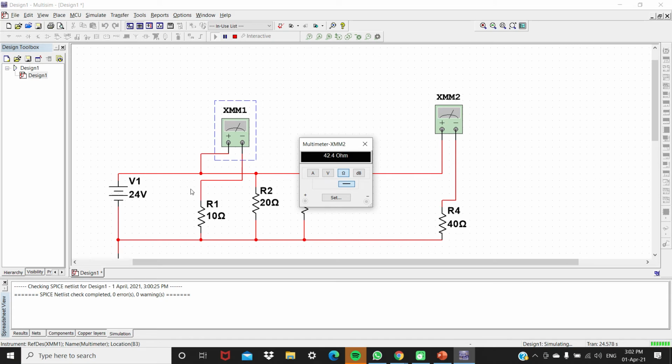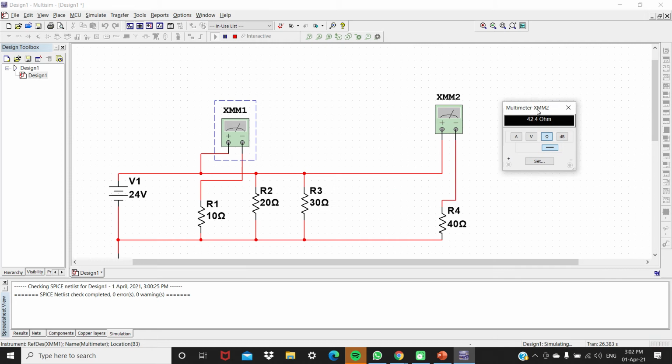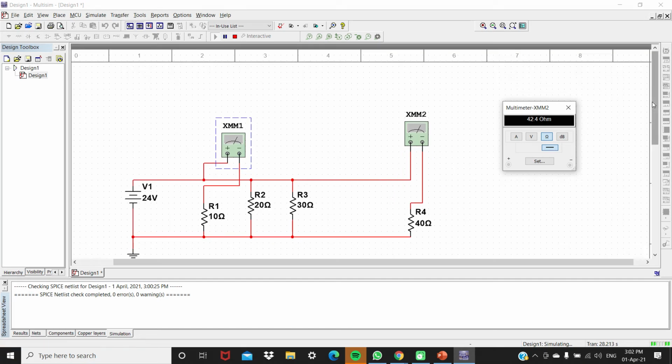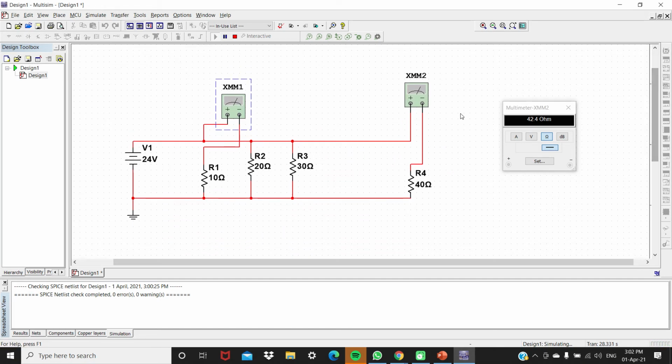2.4 ohm. I think because of the DC. Okay, yeah, because of the connection and the wires. You remember the resistance itself is 40 ohms, but the wire that you are connecting to it in reality should have some resistance on its own. That's why you get the 2.4 ohms. It's because of that wire that you're connecting to the probe.